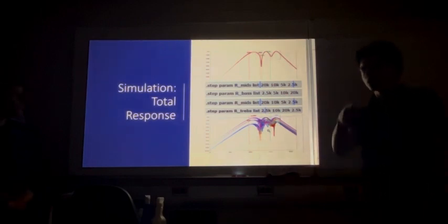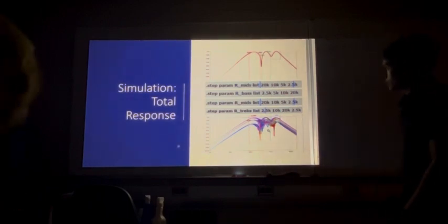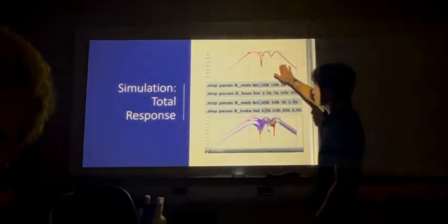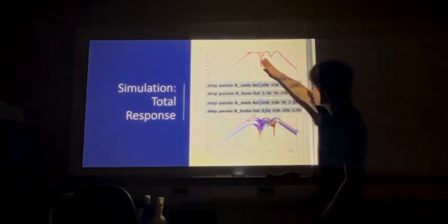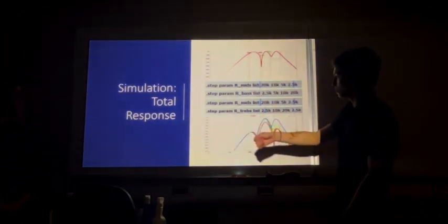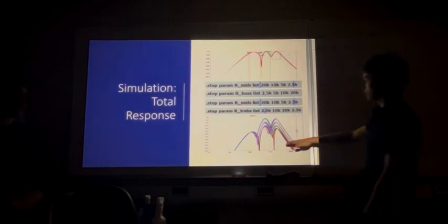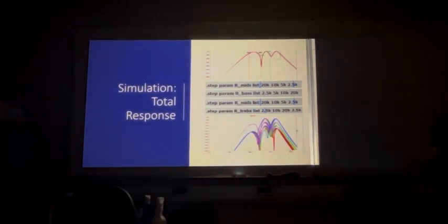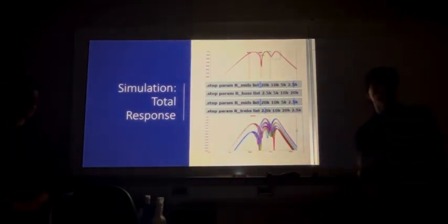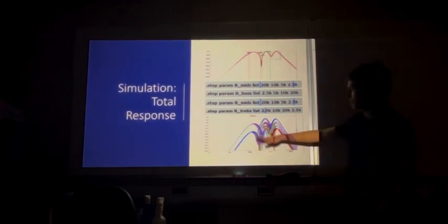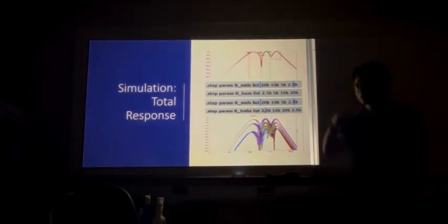We have another video here if you don't mind playing that. So idea being, this is our total response when we actually sum it all. Now we do have a notch here, but that can be fixed just by our boost value. So here we have a simulation of all the combinations that we could possibly have with different R boost values. So as you see, the notch goes away when the bass is amplified.